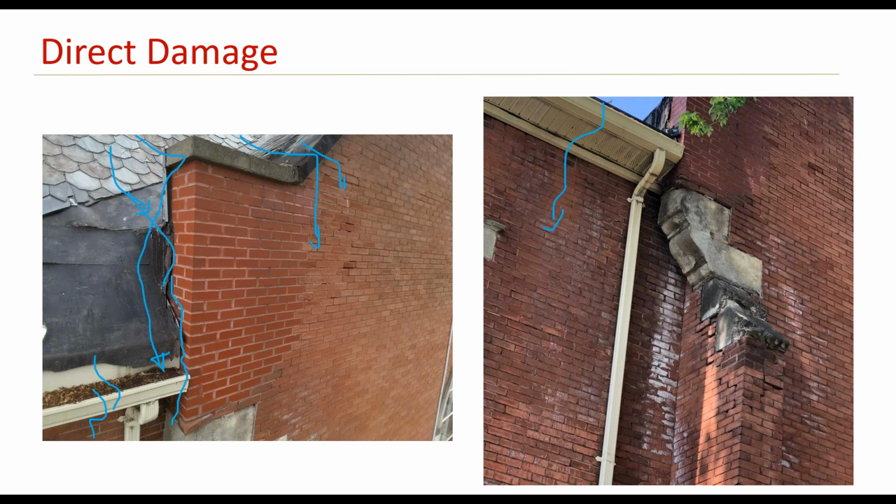This moisture would start dissolving the salts and minerals within the brick veneer. Then when it comes to a drier day or a warmer day and the water starts evaporating from the brick veneer, it would wash out all the salts and the minerals that are an important part of the structure of the brick veneer units. And you see these salt formation, we call them efflorescence. This is a major sign that you have moisture movement in and out within the brick themselves.